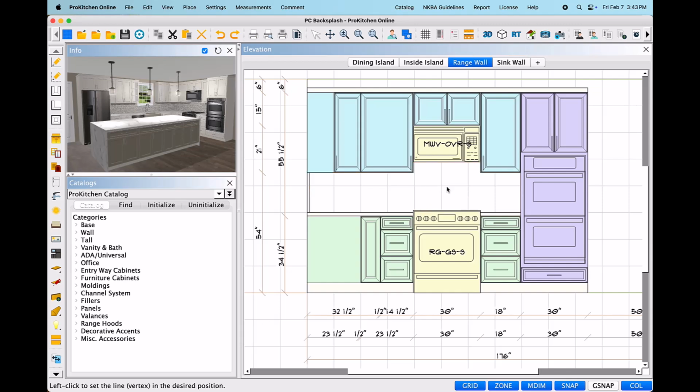If you're not satisfied with the shape of the curve after securing it in place, left-click the point at the center of the curve to adjust the depth and shape of the rounded edge once more. Now let's explore the additional subset of edit tools for the points on the backsplash. To activate, hover the mouse over the desired point and right-click.